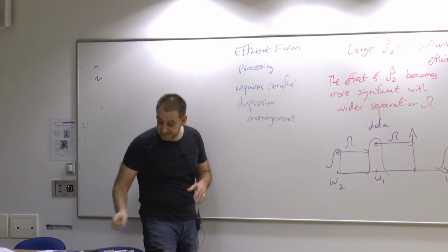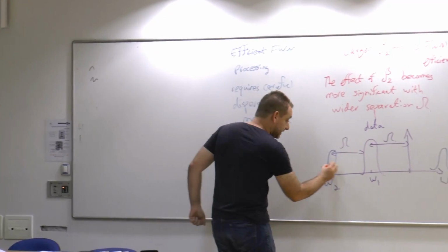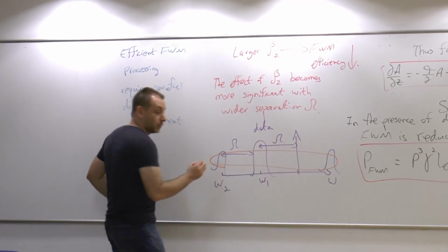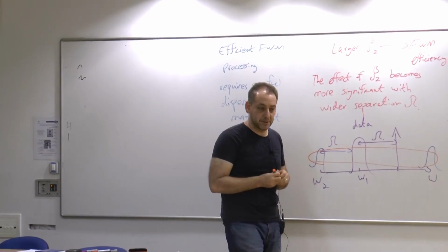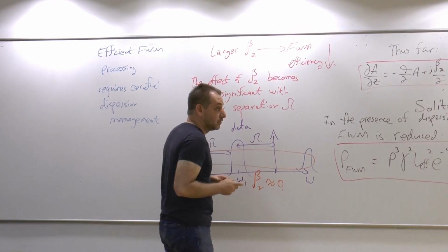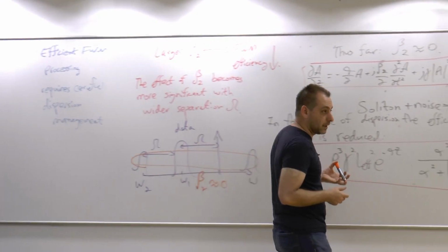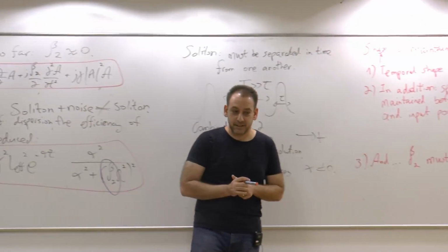So we will make it our business to design the waveguide very carefully so that at least within that span of omegas, we have a very small chromatic dispersion. So beta 2 will be preferably close to zero. So yes, again, one man's noise is another man's signal, famous statement in action again.